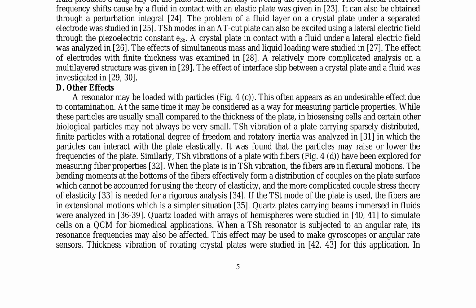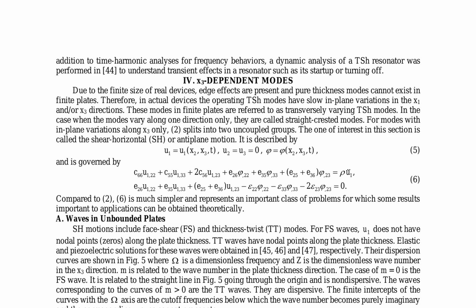Other effects, such as particle loading, fiber loading, and angular rate, are also considered. Particle loading can raise or lower the frequencies of the plate, while fiber loading can be used to measure fiber properties. Angular rate can affect the resonance frequencies of a TSH resonator, making it suitable for gyroscopes or angular rate sensors. The paper also discusses X3-dependent modes, which are necessary due to the finite size of real devices, where edge effects are present and pure thickness modes cannot exist.